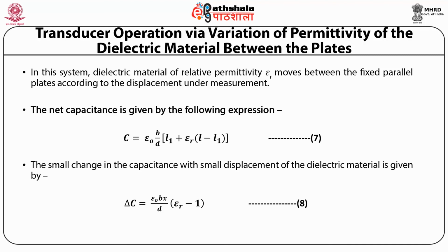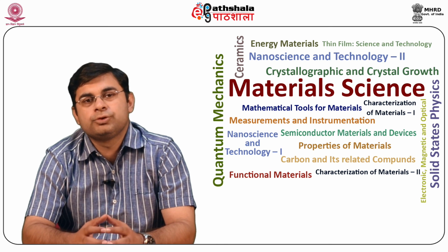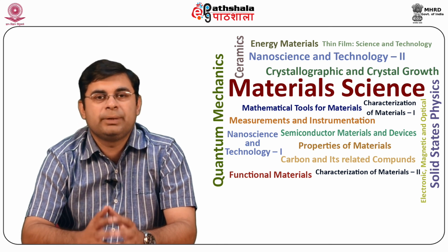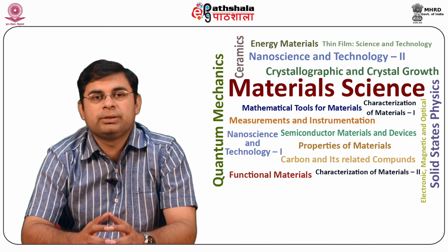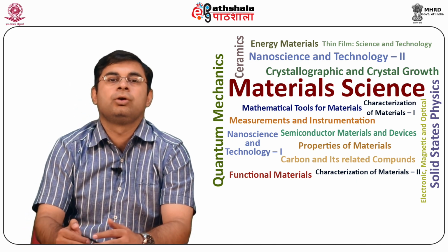This is equation 8. Change in displacement is proportional to the change in capacitance. This method can be used to measure displacement from 1 micron to 10 mm.